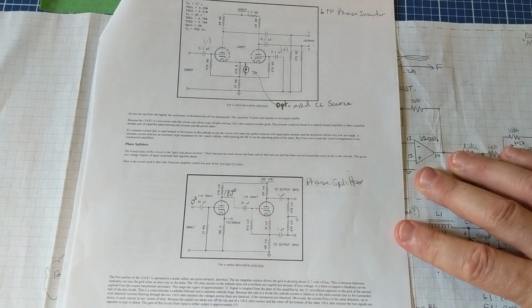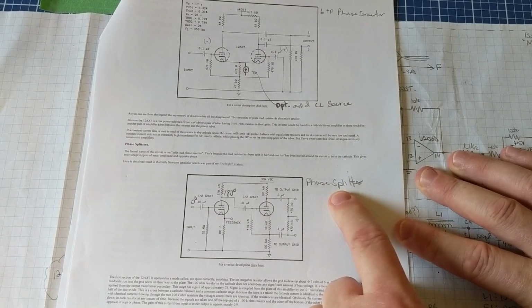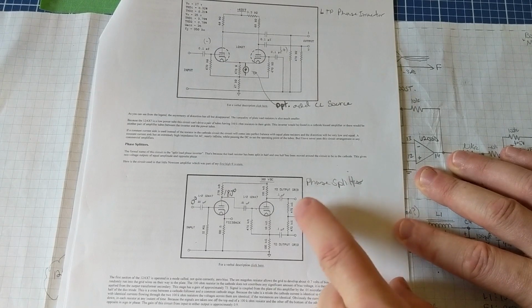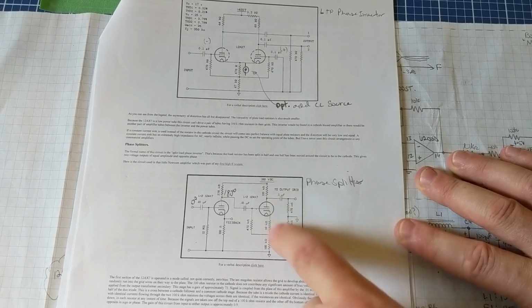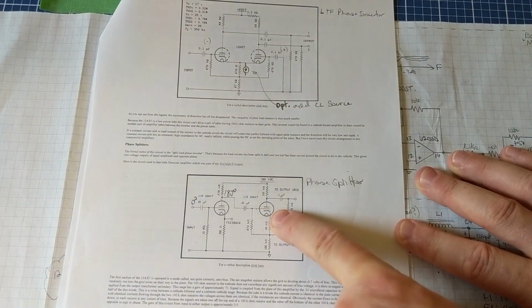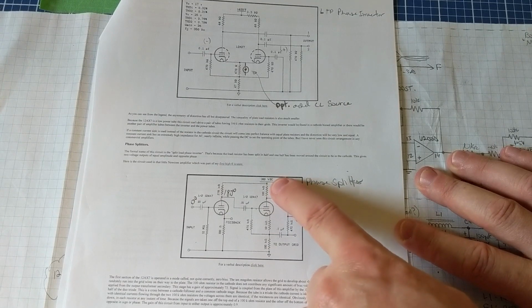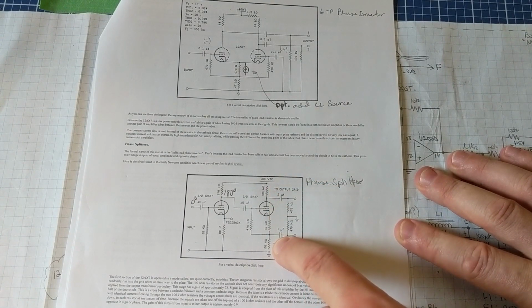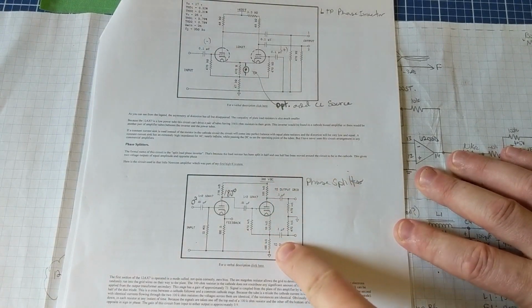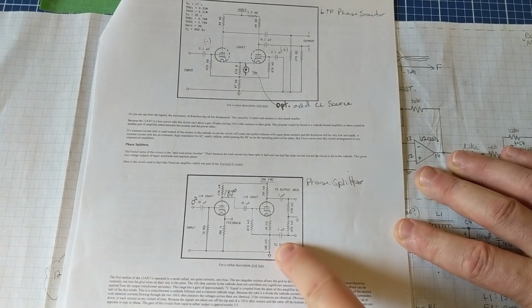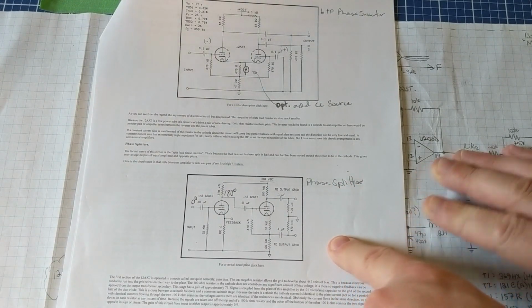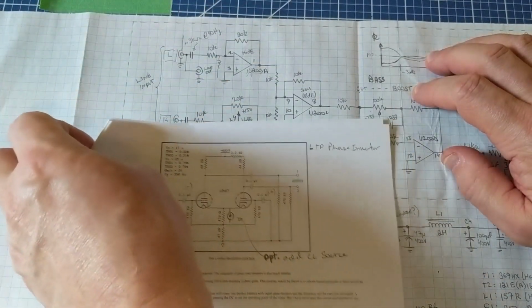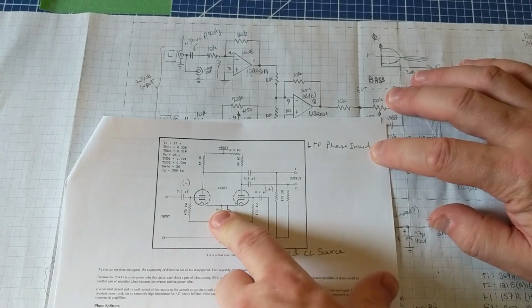The other design for a circuit that gives you the 0 degree and 180 degree signal is called a phase splitter, and you see this on other circuits. I've seen this in, for example, tube amplifiers, where the outputs are actually taken from both the top and the bottom of one triode only. In this case, the voltage drops across the upper and lower voltage divider resistors. You want to keep those matched, because the goal of a phase inverter or phase splitter is to have 0 degree and 180 degree outputs, but they should match in amplitude to one another. So from the notes on this one, I use this as the design for my amp.